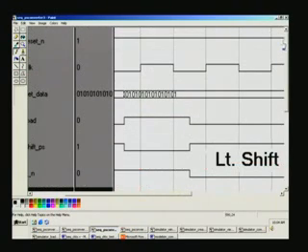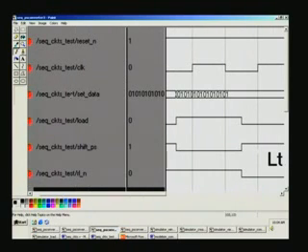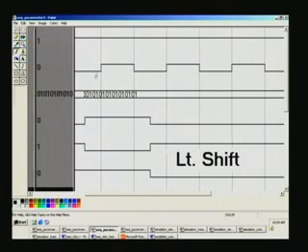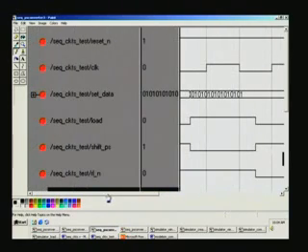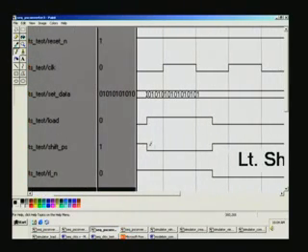Now this time we are not loading 1010, this is data loaded, you can see set data, and what we load now is 0, 1, 0, just opposite of the previous content, and this is the load asserted, and shift starts being active right from here the moment it is loaded. So shift register must start with this value to start.